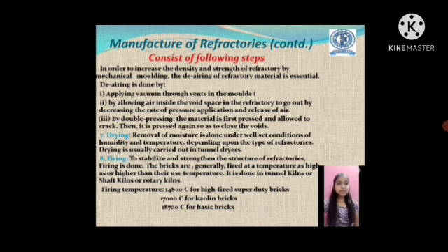Seventh, drying. Removal of moisture is done under well set conditions of humidity and temperature, depending upon the types of refractories. Drying is usually carried out in tunnel dryers. Eighth, firing.